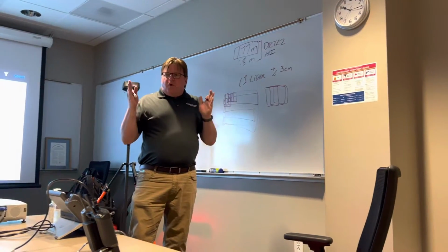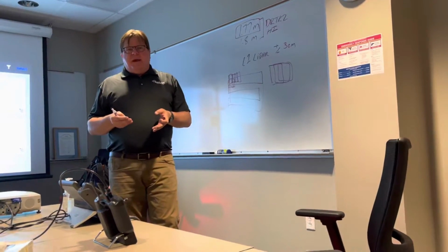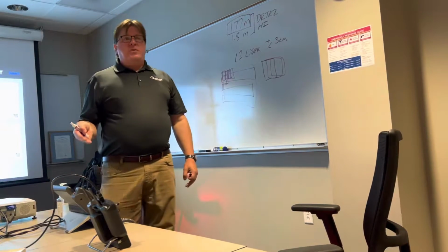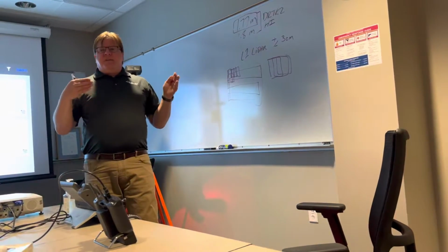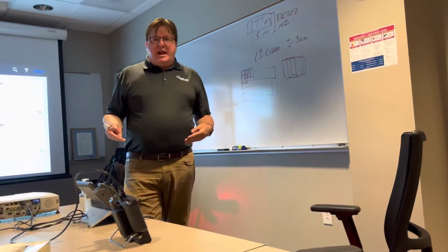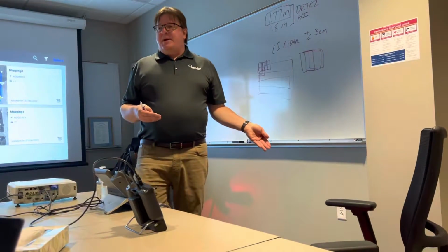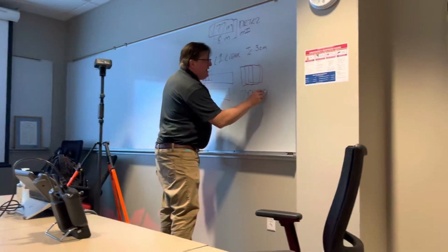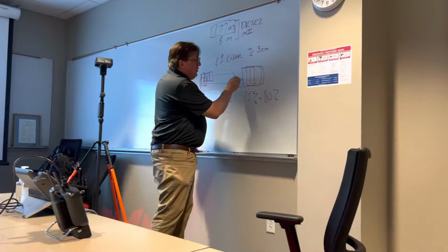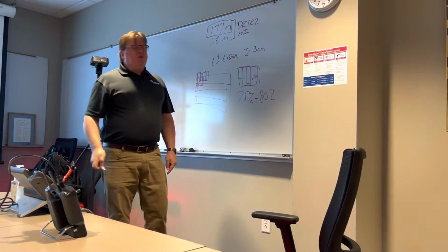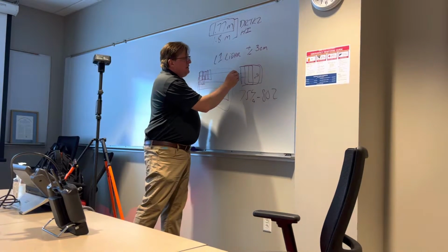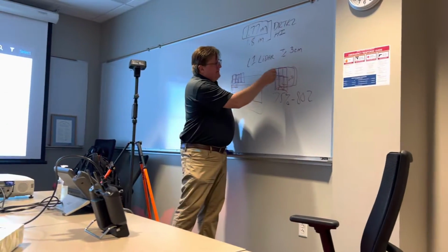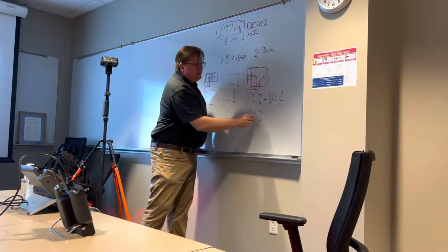The tighter your overlap, the better your model is going to be. Unfortunately, the more photos you have to process and the more complex the model becomes. So there's a fine line: this is the limited number of photos I have to take to get a really good, accurate model without going overboard. Typically that is going to be a 75 to 80% lap going forward. We're also going to intermix those with different flight lines on the next run. This side lap is going to be 70%.